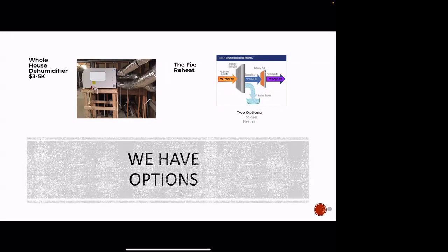And obviously the first one that we typically will go to and talk about is whole house dehumidification. Understand when we're installing a whole house dehumidifier, though, we can either do it in dedicated areas, which is my personal favorite choice of installing them. If the HVAC system's the right size and everything with load, that's going to take care of the living spaces, and the whole house dehumidifiers do spot dehumidification in crawl spaces or basements.